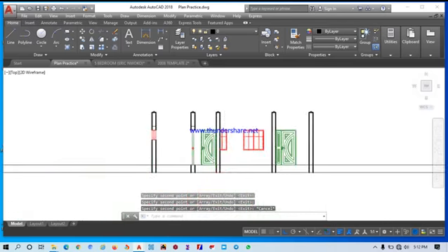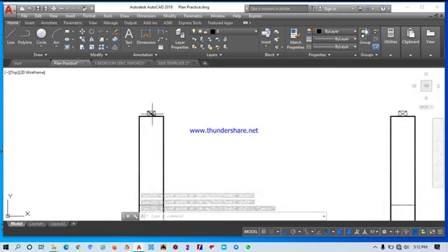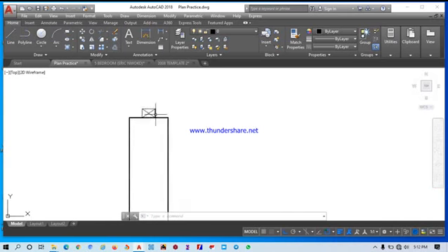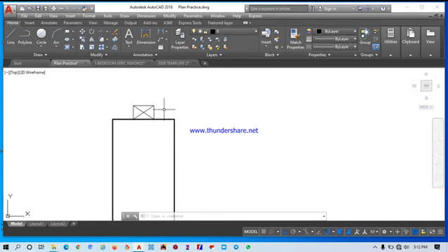Here is our wall plate. It is this wall plate that is carrying the load of the building. It is linked. All the other roof members are linked to each other. They are connected. They are interwoven. So the rafter will be resting on this wall plate later, and we have a kind of tie, a steel or a reinforcement of maybe 4 mm or 6 mm, that is in our beam.